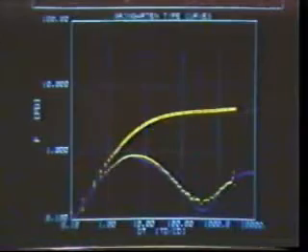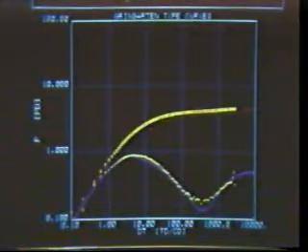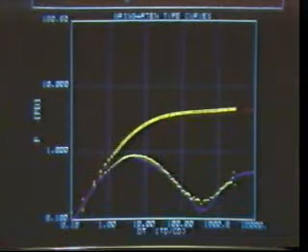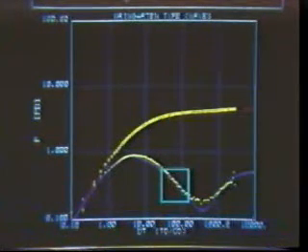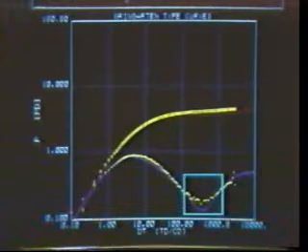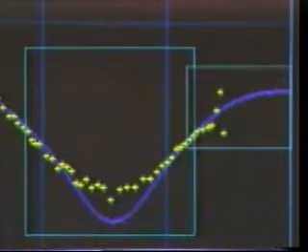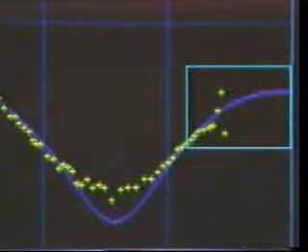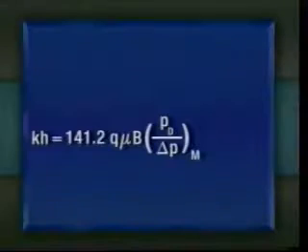The most defining characteristic of dual porosity is to be found on the derivative plot, the trough, here. After wellbore storage effects have ended, the curve indicates 3 flow periods. First, a period during which flow to the wellbore is contributed exclusively by the fissure system. Next, a period of transitional flow behavior. And last, a total system flow period, during which flow into the wellbore is contributed by both fissure and matrix systems.